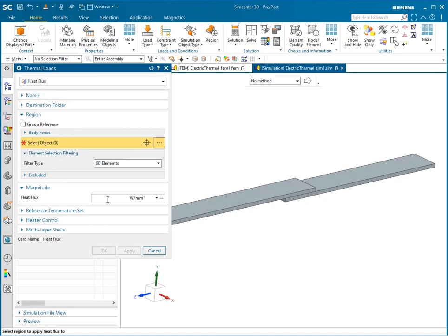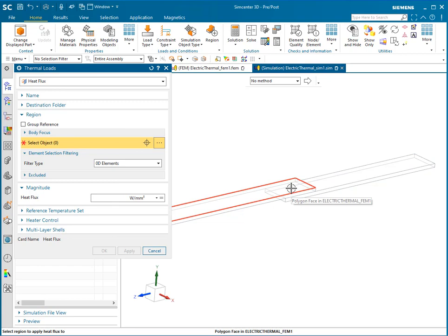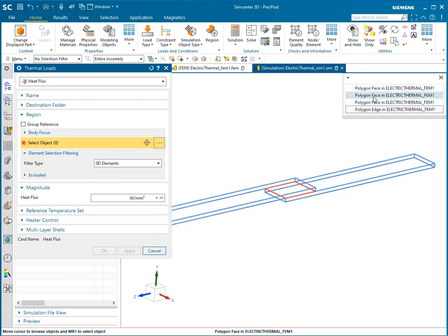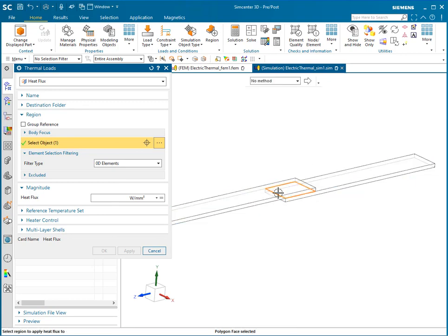This one wants units of type watt per millimeter square. So this one corresponds to our losses that come from this interface resistance. So let's use this one. So this means let's define the phase where this one will be applied. So this phase here in the between area, this is the one where we want to apply losses coming from magnetics.